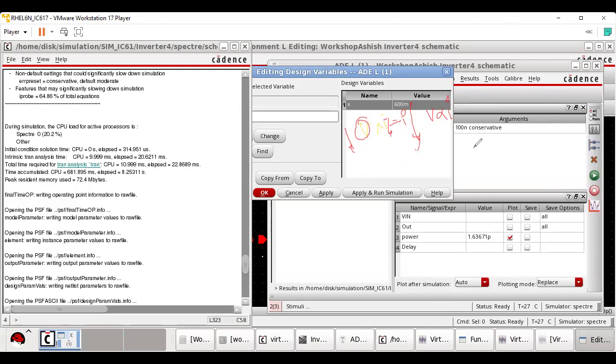So reducing the VDD is a universally accepted technique, but please remember, if you reduce it to reduce the leakage power, the delay may go haywire, right? If you do the simulation yourself, you will see that there is a huge difference between the delay given by the device at 0.6 volt and 0.5 volt, and probably it will not work at 0.4 volts, right?